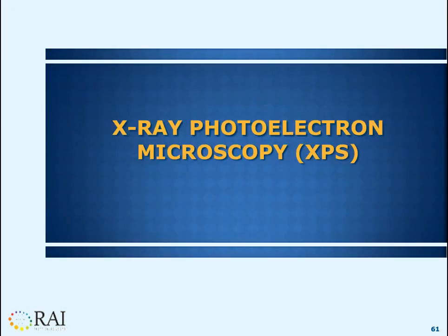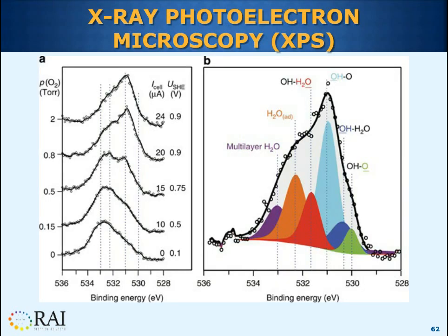And I'll talk about X-ray photoelectron spectroscopy, or XPS. XPS provides a type of information on chemical compounds that is present on the surface of a sample. Most other techniques that I spoke about today give only elemental analysis, but XPS gives chemical compound information. And by that I mean other techniques I identified today might identify sodium and chlorine, but XPS will tell me if the sodium and chlorine are chemically bound as salt or some other